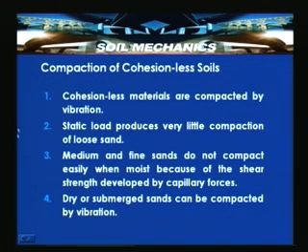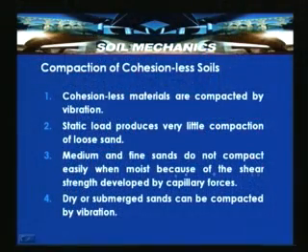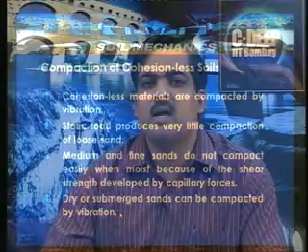Cohesionless soil materials are compacted by vibration, and static load produces very little compaction of loose sand. We have seen this through a demonstration test. Medium and fine sands do not compact easily when moist because of the shear strength developed by the capillary forces. That is what we have discussed: these films do not allow the particles to come closer. Dry or submerged sands can be compacted by vibration. Submerged sand means sand completely saturated with water, and it can be compacted by a vibration technique.